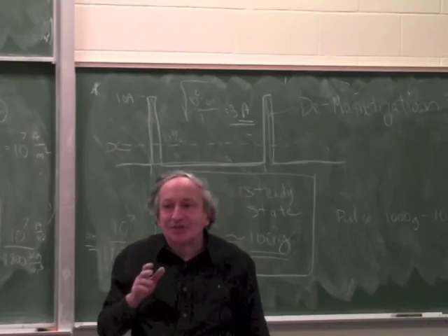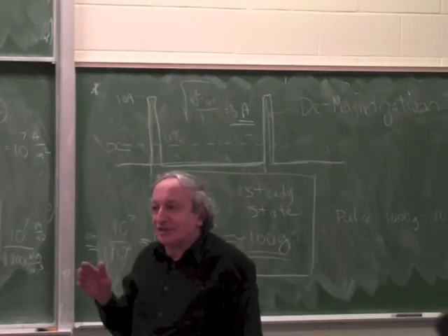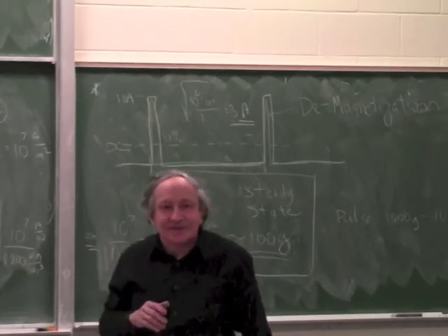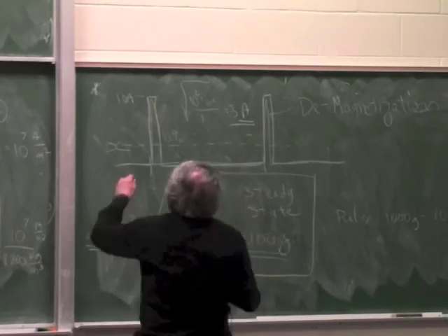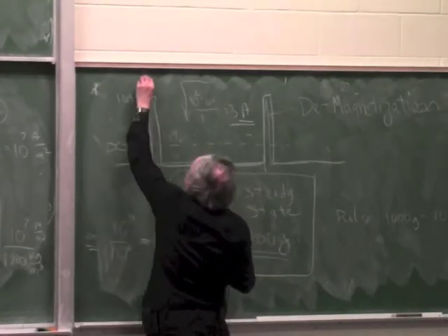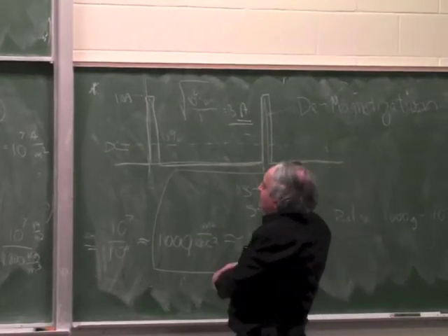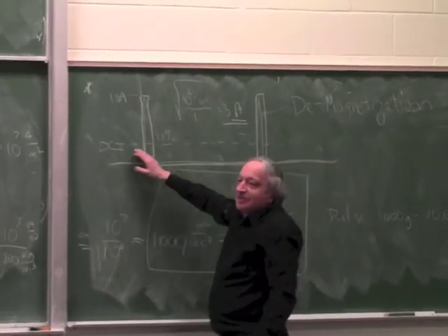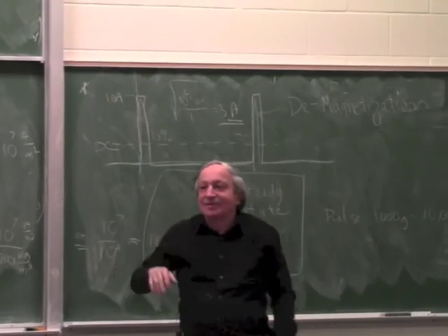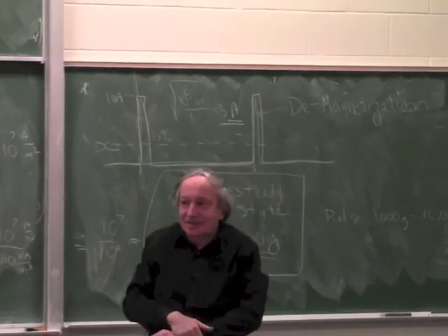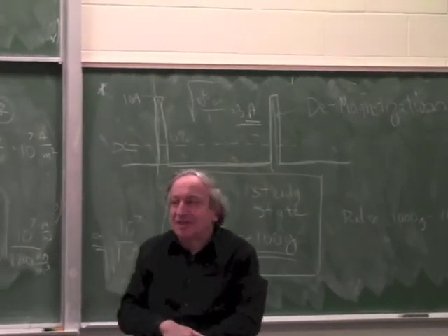So the more dangerous it is if you pick the average instead of RMS. Say if this was 100 amp for 1% of the time, the average is still going to be 1 amp, but the RMS will be 10 amp. Is that clear? That's very important when you design actuators.